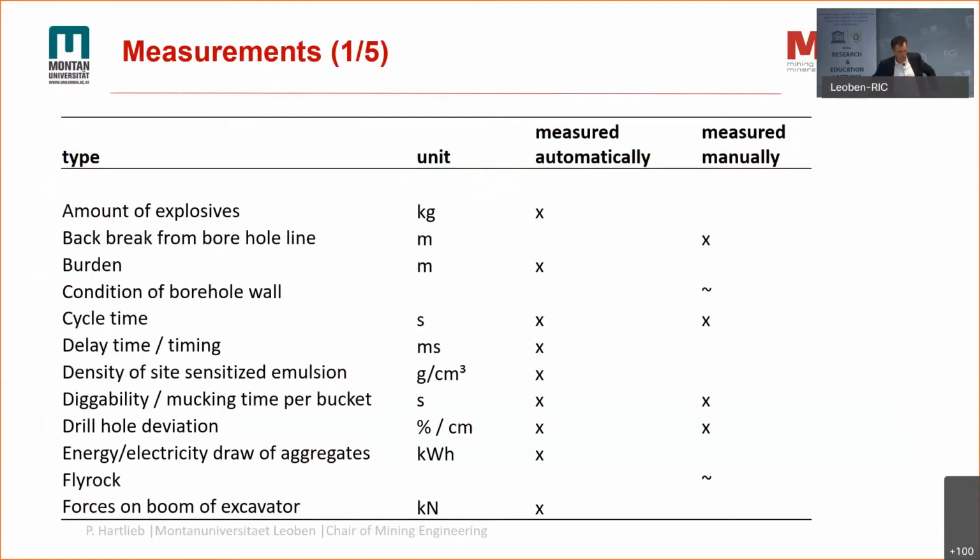So what you can see there, and I won't go into all the details, but I think many of the things that you also mentioned in your list previously, I mentioned here. From the amount of explosives, which can be measured automatically, to the back break, which is important for a blasting engineer, for example, to the burden, to the condition of the borehole wall. Delay timing is a very important part. Then there are some other very specific things, which are the diggability.